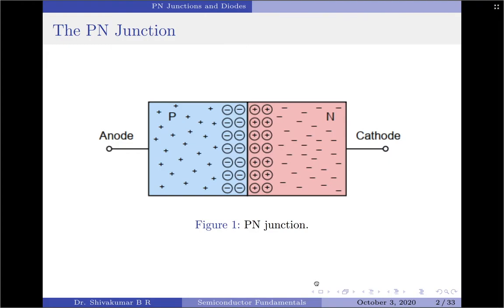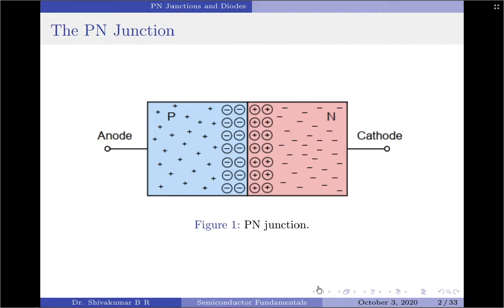It is critical to understand that when we combine p and n-type materials, we do not do so through simple mechanical means. Rather, we must maintain a single piece of monocrystalline silicon, not a polycrystalline amalgam of individual pieces. This can be achieved via a diffusion or ion implantation technique that is applied repeatedly to a single piece of silicon crystal. This will leave regions or zones in the crystal that are n-type or p-type. In fact, it is quite possible to have a region of one type completely embedded within a region of the opposite type, as we shall see in upcoming sessions.